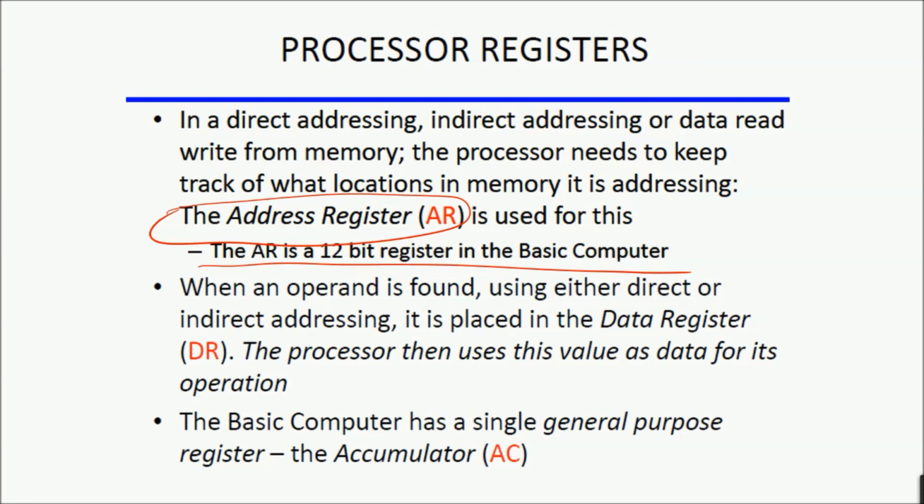Either we have to first store the contents of the address register to a temporary register, then execute a memory reference instruction, and then get the address of our instruction back from that temporary register and fetch the instruction from there. So again, we need a dedicated additional register to store the address of our next instruction. So why not use a dedicated separate register that keeps counting itself, allowing us to keep the address in that register without having to save and retrieve it again. So we are saving some clock cycles by using dedicated address registers for instruction and data.